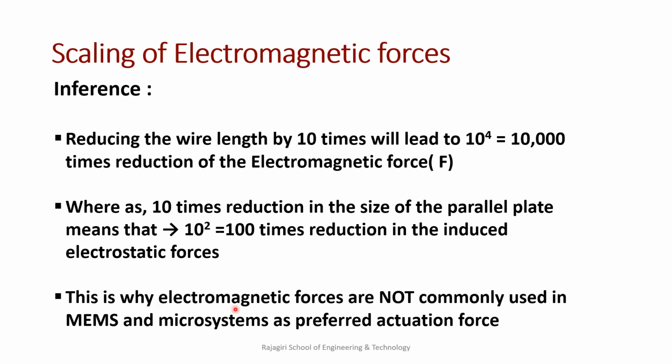And this is the reason why electromagnetic forces are not commonly used in MEMS and microsystems as the preferred actuation force, because with the reduction in the linear dimension, the reduction in the electromagnetic force produced will be much higher compared to that of the electrostatic force.